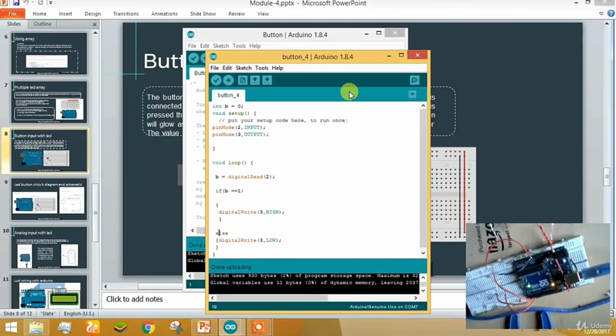It is better to use wires in place of a button for testing, because with a button you can get garbage values, or you can say micro values of initially getting high and low, causing a transient, which will give random values of high and low and make the LED flicker. This is because of the processing speed of the microcontroller, which deals in milliseconds. So removing the transient, we are directly connecting wires. Let's see once again. Now see here, it turns on, turns off, turns on, turns off.